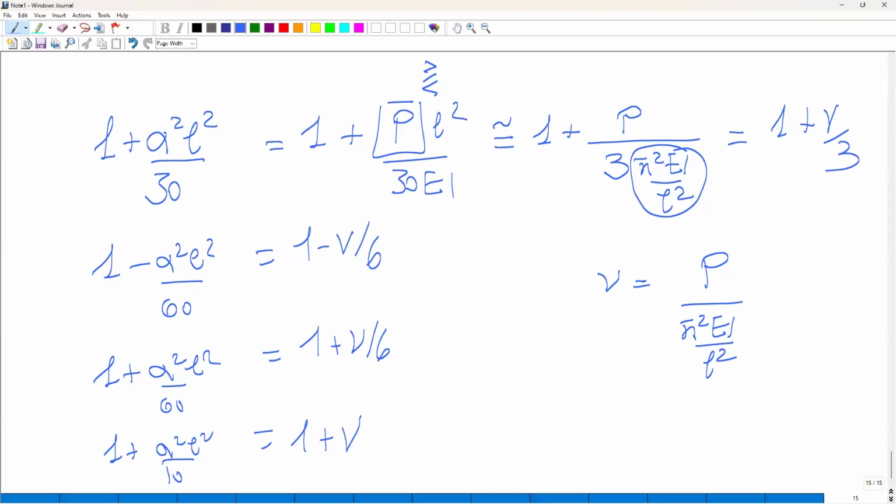When we publish a paper, made a test on concrete, we must say, okay, this is my concrete mix design. These are the properties of my constituents. This is the way in which I produced my concrete. This is the way I cured my concrete. This is the way I made my specimens. This is the way I tested my specimens. These are the results. Because anybody else should be able to repeat your same tests and find the results which either confirm your results or contradict them. This is the first way for a paper to be a scientific paper.